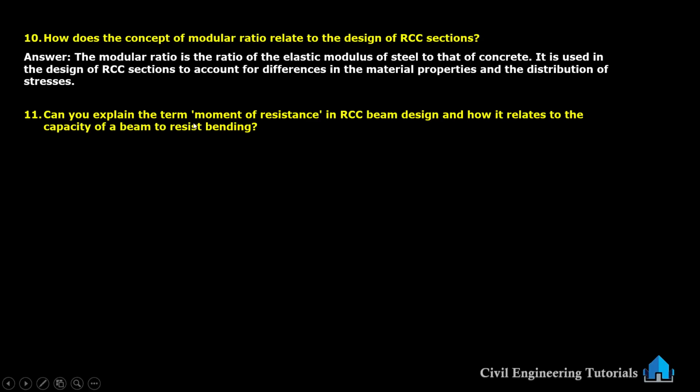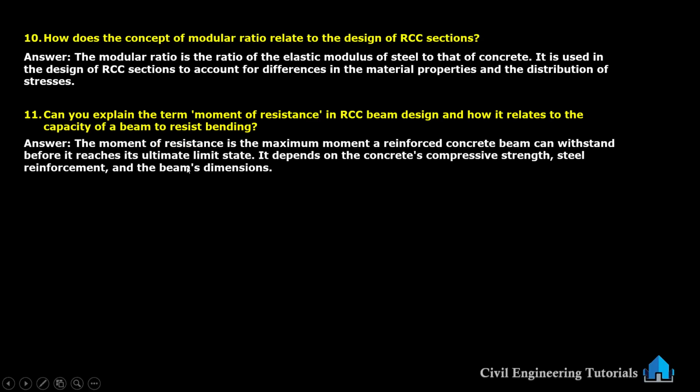Can you explain the term moment of resistance in RCC beam design and how it relates to the capacity of a beam to resist bending? The moment of resistance is the maximum moment a reinforced concrete beam can withstand before it reaches its ultimate limit state. It depends on the concrete's compressive strength, steel reinforcement and the beam's dimensions.